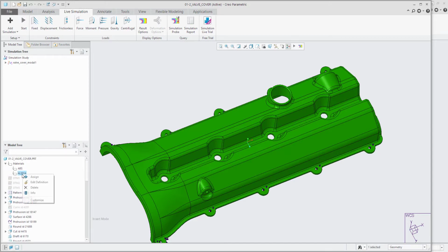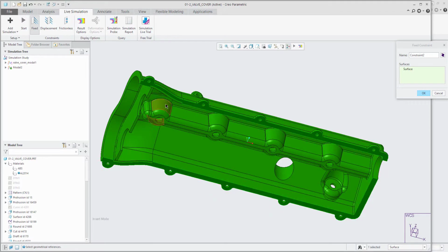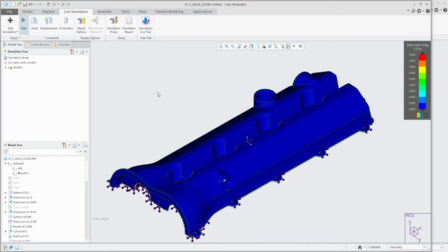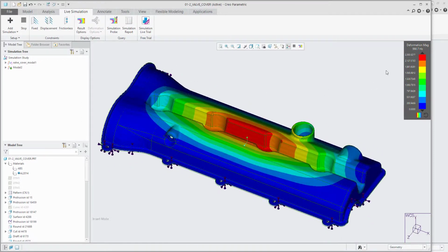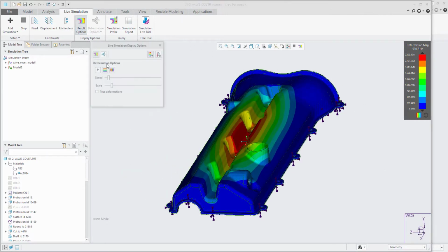So as I said, it's made out of aluminium, and what I'll do is a modal analysis and maybe just fix the face where the gasket surface would be, as it's bolted down into the car. And at this point, I can already do an analysis and get a baseline level of the first mode natural frequency, 900 hertz. So it looks something like this.